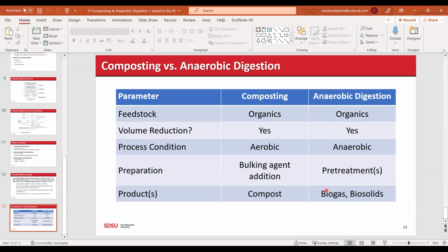So given this, we already have our Ra equation. Our Ra equation, if we didn't know it, that's our electron acceptor equation. But if we didn't know it, we could also balance it using the same steps. Make sure you can see this here. All right, so we have O2, and this is what we're starting with as our electron acceptor. Let's balance it the same way we did for the electron donor.